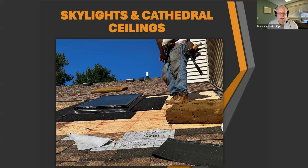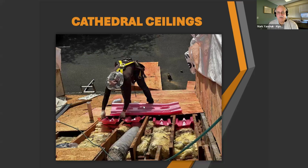This is replacing skylights, flashing around the skylights. Installing baffles at cathedral ceilings is important because the insulation may be choking off the airflow from the eave to the attic space or the ridge.